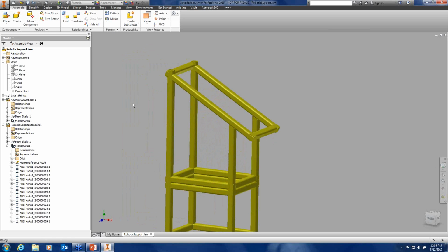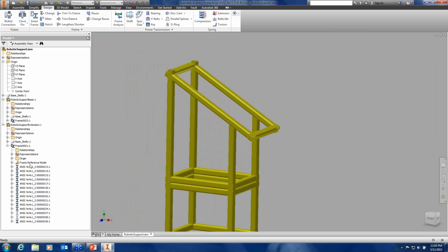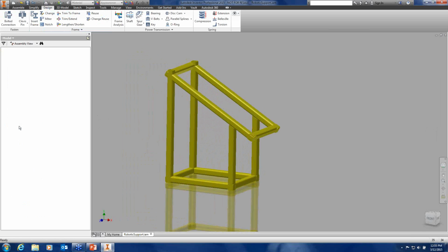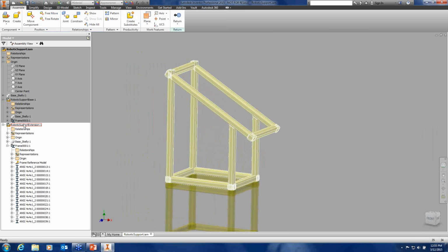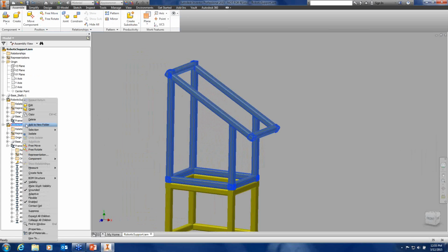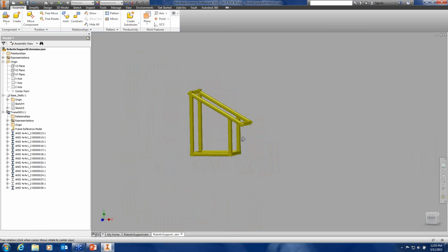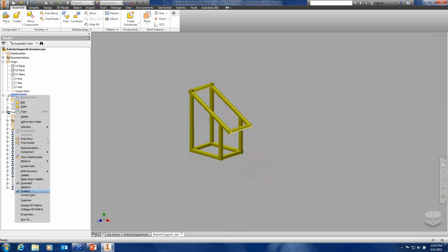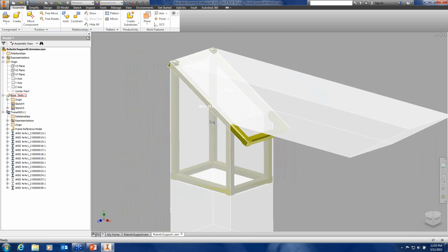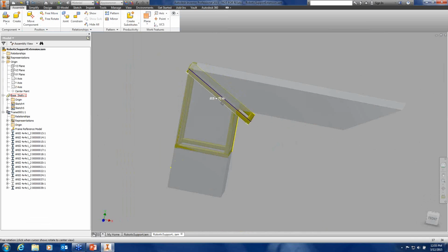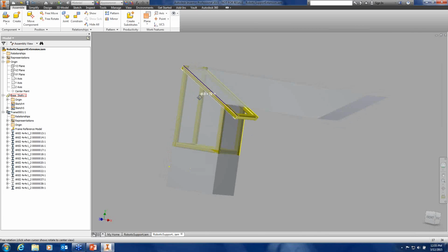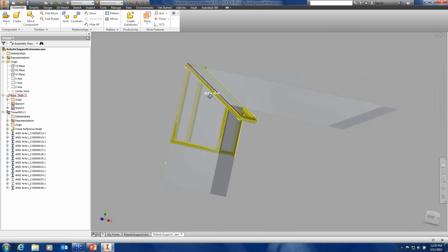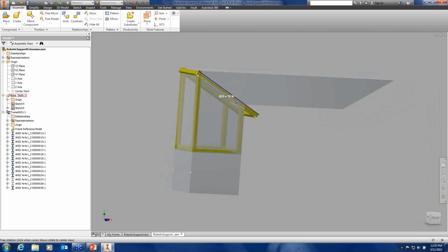Now, a few things here back to the design. Just to give you a quick idea on how I modeled this part, let me go back up here and do that and right click and just open it up separately. Here's the part as it was modeled. I will turn the skeleton back on so that you can see how that was actually laid out. And so here once again I used the edges of the solids and again stayed inside of the boxes, so that these things could be shipped separately and assembled on the field.